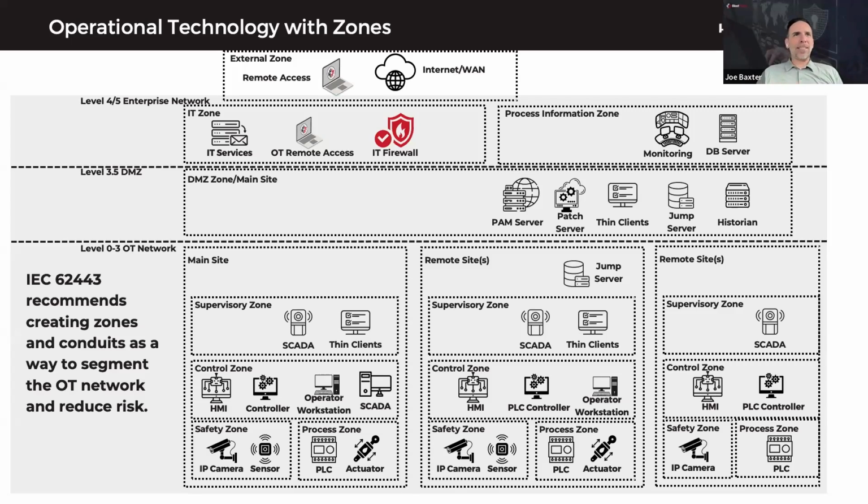How do I group these devices or these cyber assets into something that even approaches some type of rationality, whether it's by manufacturer and then below that, endpoints like PLCs, RTUs, or whatever it might be, SCADA servers, that kind of thing. There's going to be zones with security and surveillance in them, oftentimes running intermingled with these types of devices inside plants because networking resources aren't infinite. You're not going to have 45 different networks in parallel with only a few devices each.